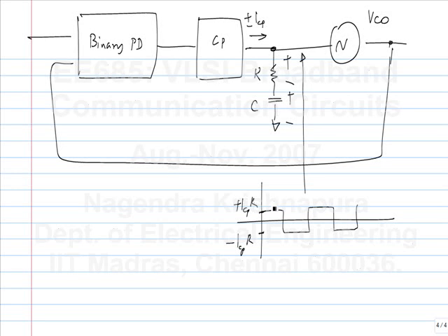What is the effect of this on the VCO? So let's say the transition density is 1. Okay. That is, you have alternating data. Now CDR analysis is further complicated by the random input data. Okay. So for this purpose, let's assume that the input data is a 1010 pattern. So what happens to the VCO phase?